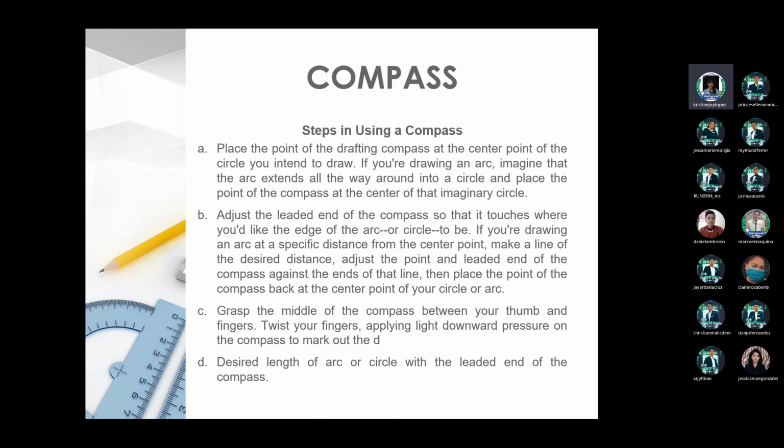So the first one is place the point of the drafting compass at the center point of the circle you intend to draw. If you're drawing an arc, imagine that arc extended all the way around into a circle and place the point of the compass at the center of that imaginary circle.